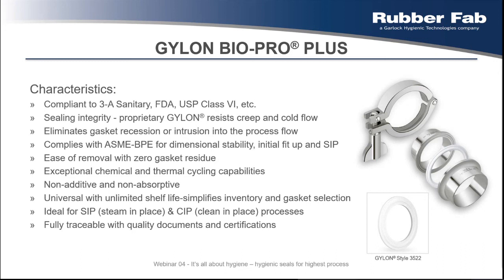Like I said before, the GYLON materials, because of their unique manufacturing process, resist creep and cold flow very well, which in return eliminates gasket intrusion in the process flow. The product complies with ASME BPE standards.